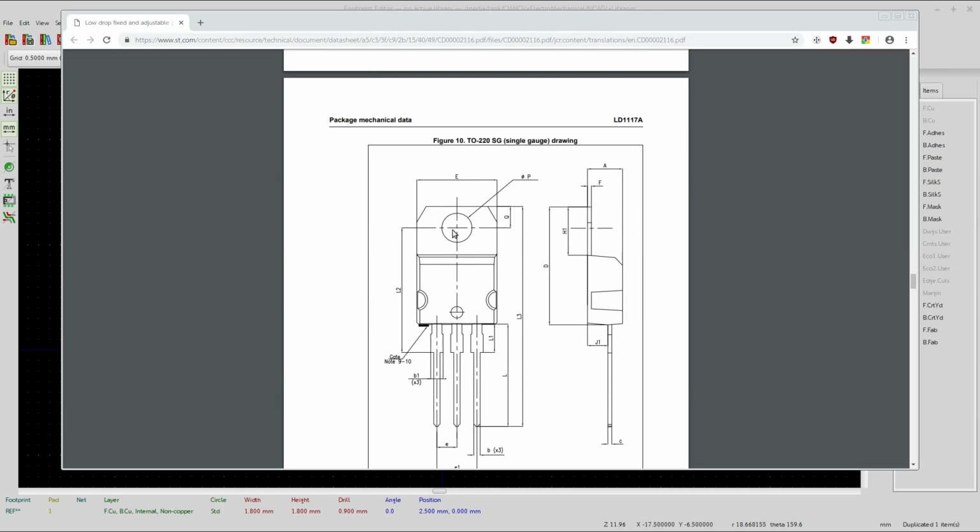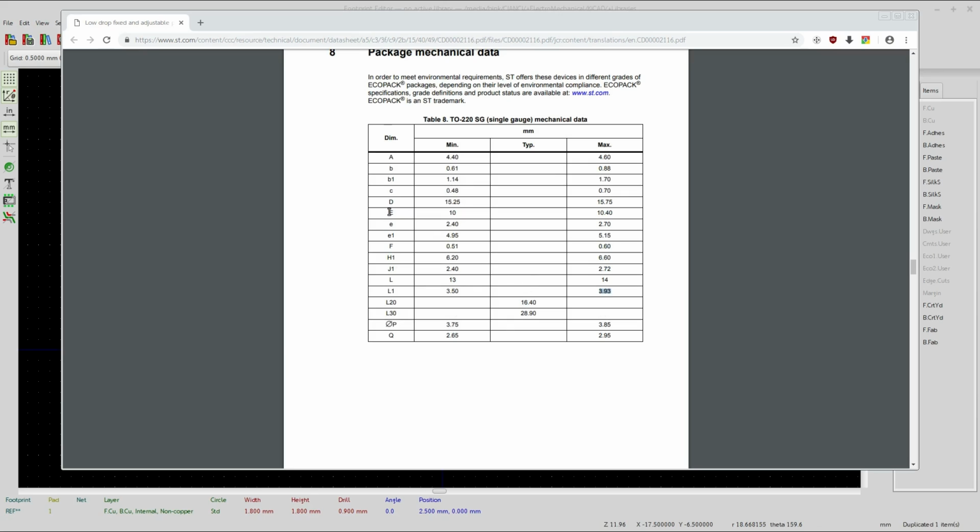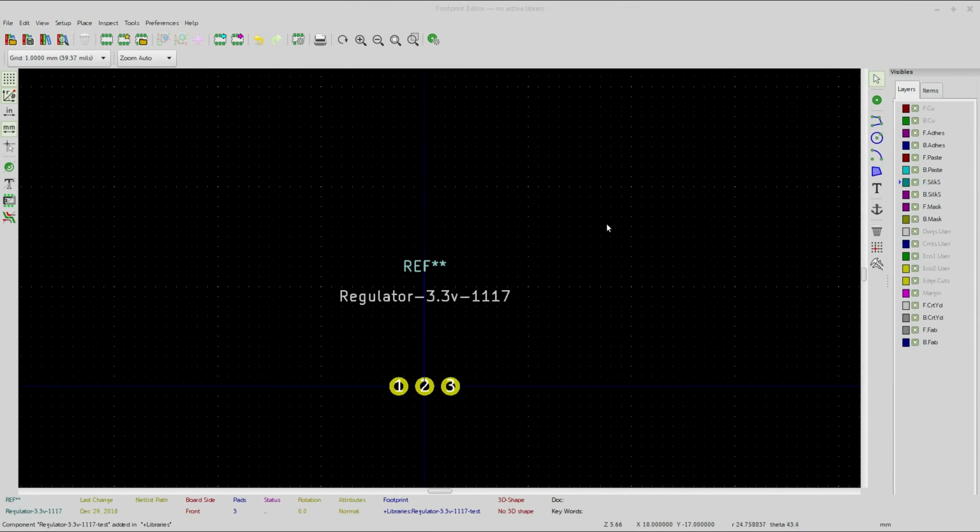And then for the width of the thing, that's going to be E. So capital E right here, 10-ish. Now, again, the reason why I'm not worried about super accuracy, I like the things to be a little bit bigger. So when it's laying down on it, you can see the outline around the package, so you know that it got set in the right place, I guess. So if we went with 11 or 12, I'm going to say 12. So we'll go 12 by 20. Now we need to make a 20 by 12 box around here to tell us where the part is going to sit.